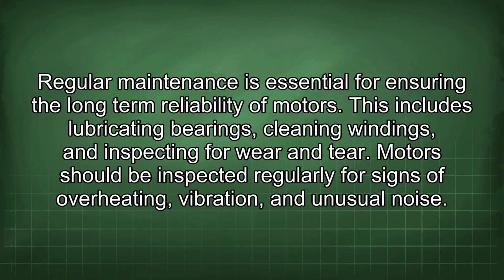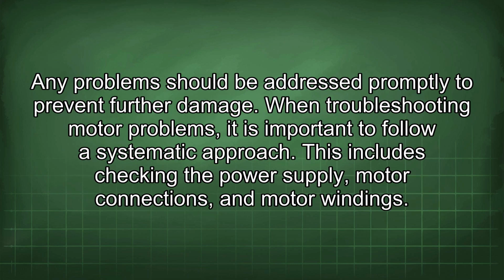Regular maintenance is essential for ensuring the long-term reliability of motors. This includes lubricating bearings, cleaning windings, and inspecting for wear and tear. Motors should be inspected regularly for signs of overheating, vibration, and unusual noise. Any problems should be addressed promptly to prevent further damage.